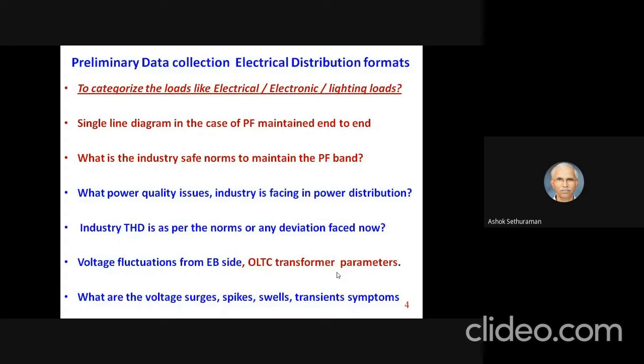The single line diagram, power factor, leave alone the capacitors. We take the case of power factor: what is maintained at the machines, what is maintained at the distribution boards, what is maintained at the SSB and at the powerhouse. This is an area where the loss in electrical distribution can be seen visibly by you in the first hour or two of the industry where you are. See, the random survey of the given industry before the audit, or during the opening session or the first day of the audit, these are all things that are already available to you.